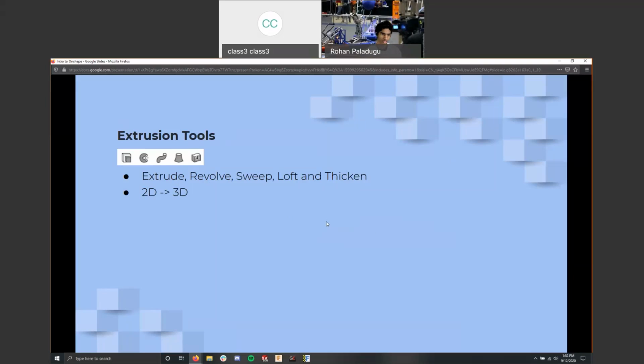Well, if you think back to geometry class, we know that if we were to rotate that a certain amount of times, we would get the appearance of a cylinder, right? So that's what the revolve tool does. I would select the revolve tool, then select that sketch, and make it go 360 degrees because I want a fully closed cylinder. I want the radius of the cylinder to be 0.25 inches. Let's say the diameter of the shaft is 0.5 inches, so half an inch. So I do that, and I got my shaft.